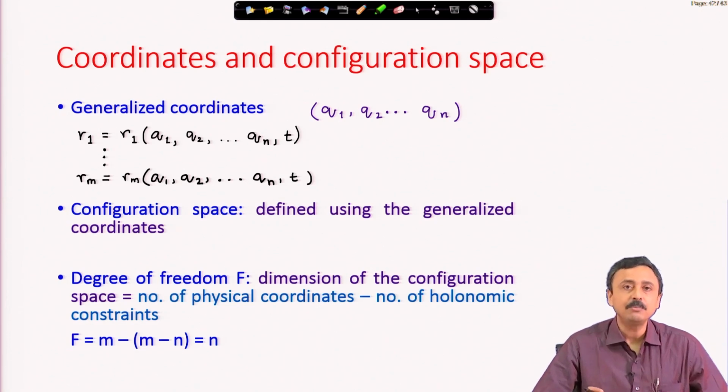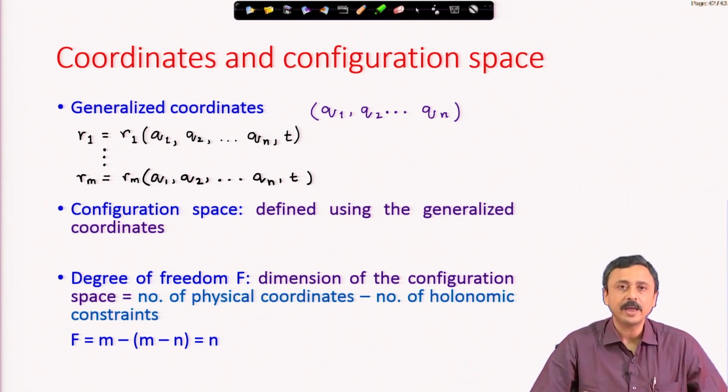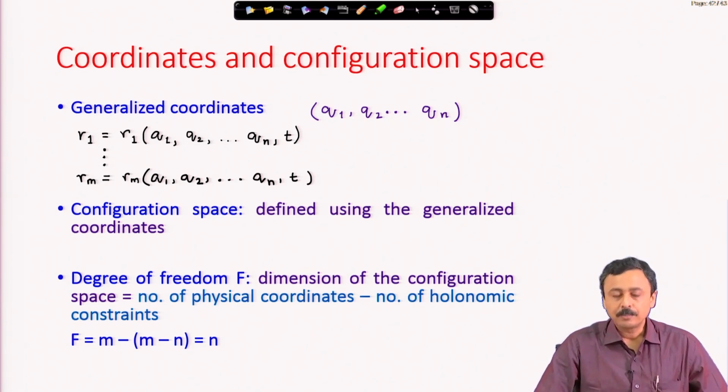We cannot arbitrarily move the car, but I can drive a car and take it to any arbitrary configuration. There is no constraint. I can take it to any location on the plane and in any orientation. I can drive it to that specified location and orientation, but I cannot push it, I cannot just slide the car to that orientation, that is not allowed, that is not a dynamical path.